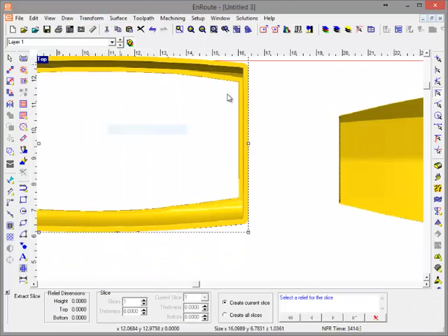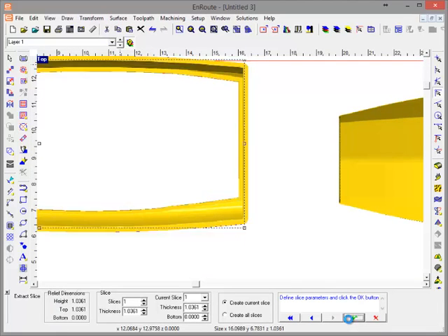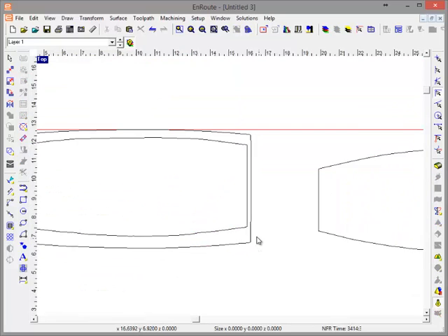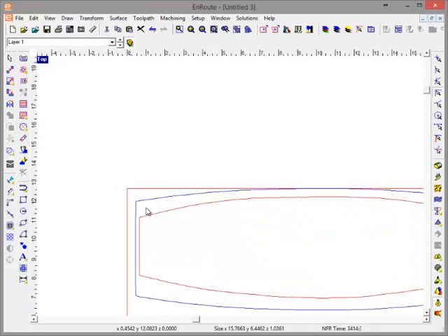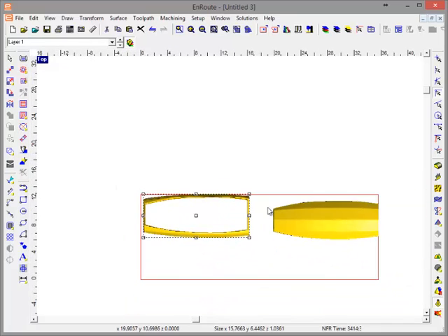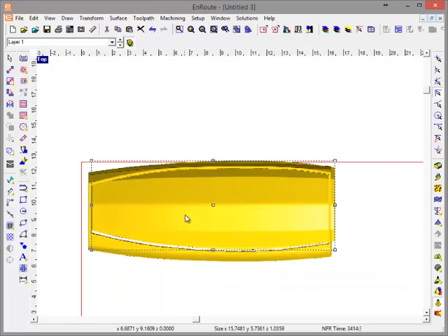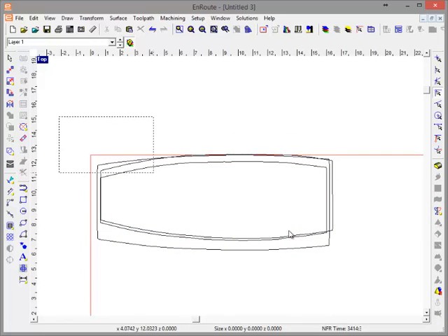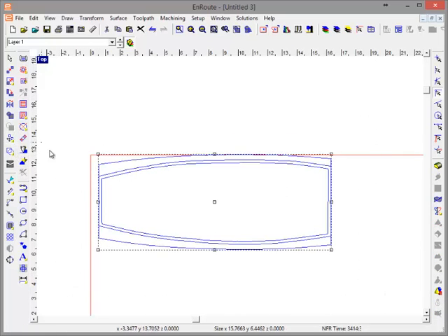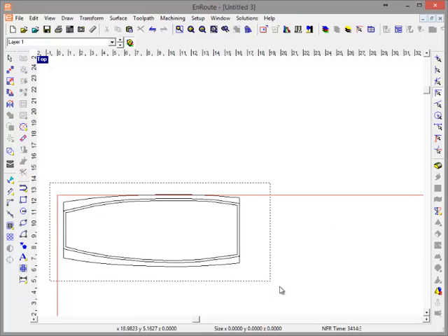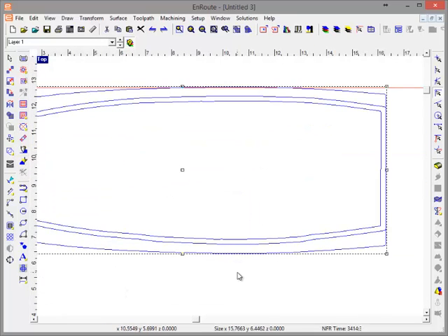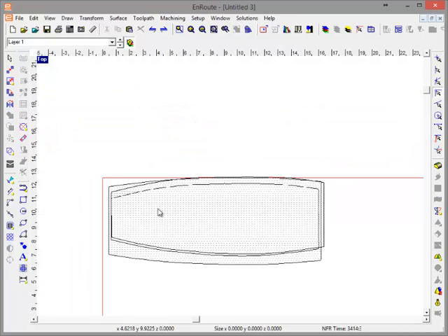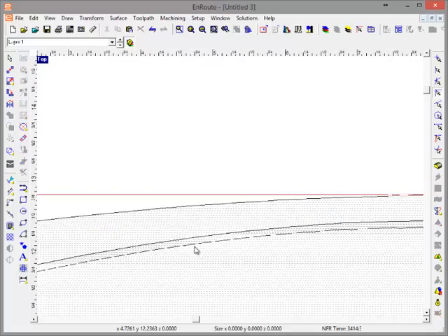Surface, extract slices from here, and check mark. All right, so I should be able to cut this one out, and then do a cutout on it, and then take this one and put it right on top of there, and it looks like that's where that little extra thickness will help, because you would need to be able to have some kind of a, so I accidentally deleted my reliefs there. You'd have some kind of overlap there so that you'll have something for this one to rest on.